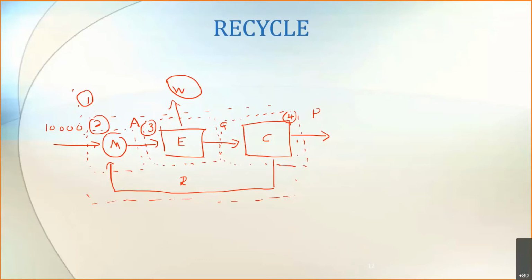This is where you do degree of freedom analysis. I'm not going to do the degree of freedom analysis here; you can try it yourself. Anyway, I'm telling you that the easiest way for me to solve is by using the overall system. And just looking at this evaporation system, my evaporator, I know that I have more unknowns than independent equations, because I have the value of A, the value of W, and the value of G, which are unknown.